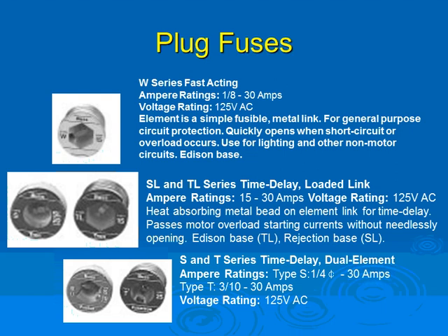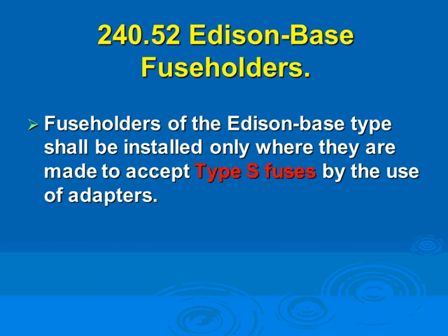So that's your plug type of fuses, and it has to be limited to, again, it accepts 15, 20, and 30 amp fuses. With the S type, amp rating, you cannot put a 20 amp fuse in a place where a 15 amp fuse should be. So you overfuse it. That's your S type, limiting you. If it's a number 14, 15 amp fuse, it will be limited.